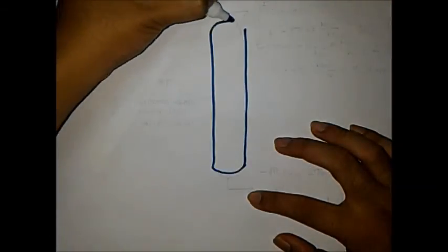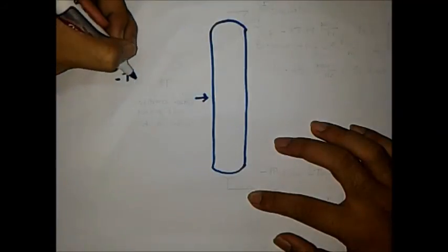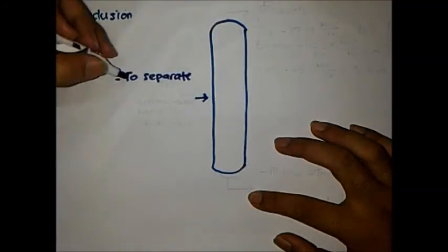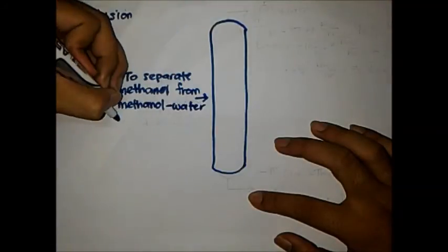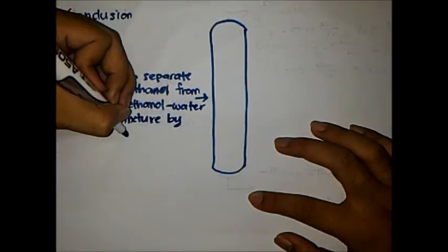The objective of this project is to study the distillation process of a methanol and water mixture. Since methanol and water have a very distinct difference in boiling point, it is suitable to use the distillation process as the separation method. The content of methanol obtained at the top section is 96 mol percent and 2 mol percent at the bottom section. Apart from that, the flow rate for all sections was calculated, with the value given at the feed section being 250 kilomole per hour.